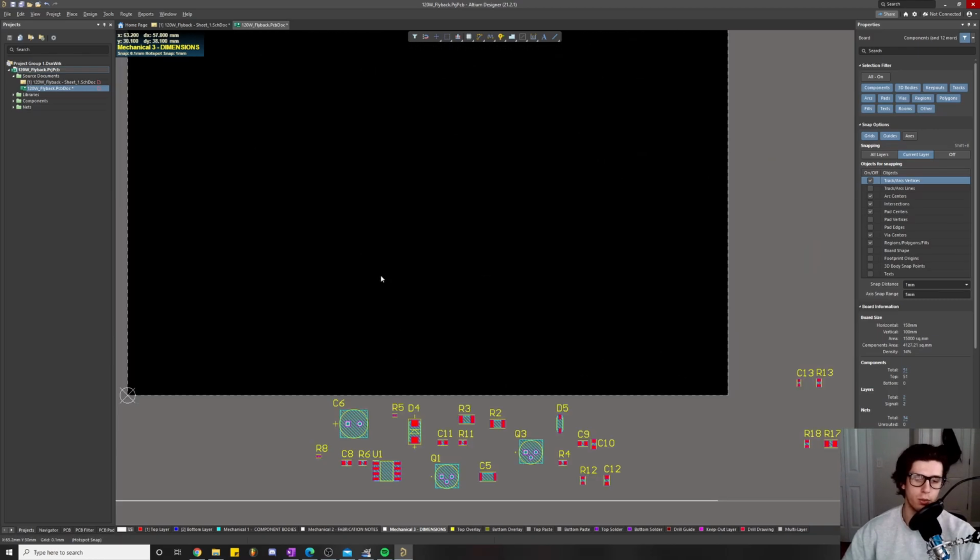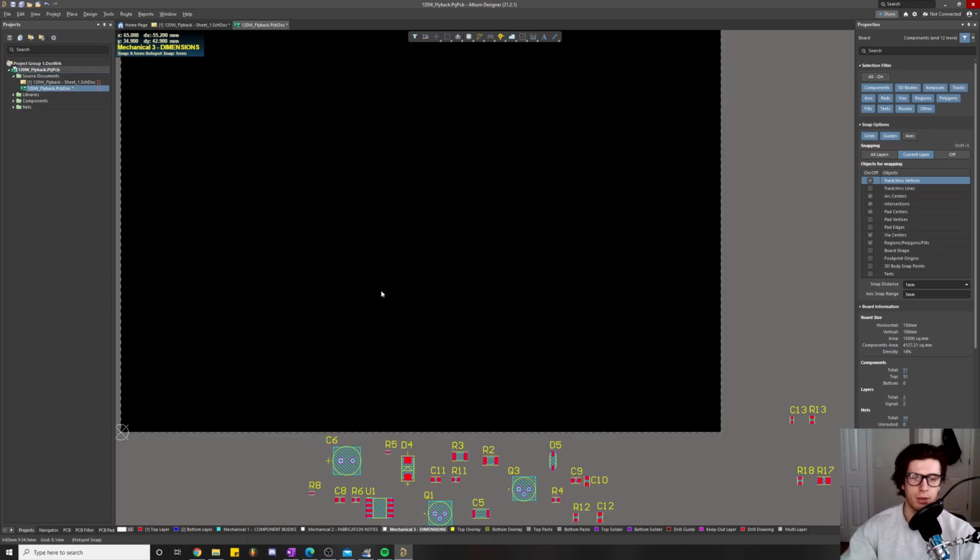So don't place those hot components right on top of each other, because the concentration of high amounts of thermal energy will cause a lot of problems for the real life user experience. They pick up the power supply and it's hot in their hand, and they don't like that.